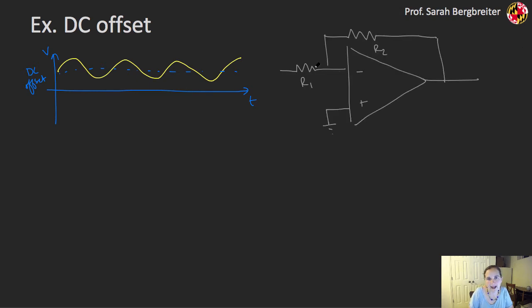So the problem that I have if I hook this up to a standard inverting amplifier topology is that if I have, say, this DC offset somewhere on the order of 3 volts here, and the small AC component that I'm trying to amplify, that's the signal ultimately that I'm interested in, that's only varying something like a couple millivolts. So I need a fair amount of gain out of this, so say maybe 10 to 1 or 100 to 1 gain. But by the time I've done that, even if I do a 10 to 1 gain, what I'm really amplifying is that 3 volt DC offset as well.